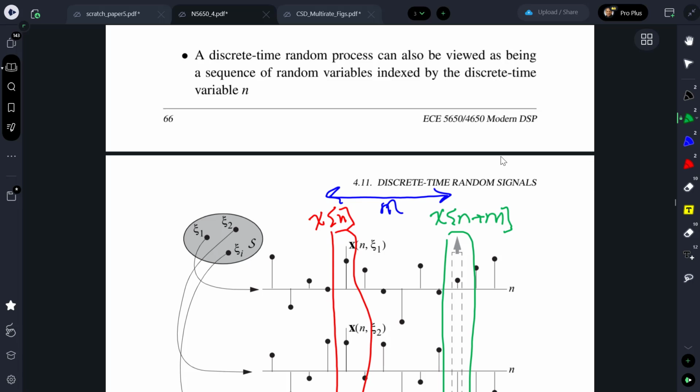A big exception to that would be if the processes have a periodicity to them, and that's called a cyclostationary property, where there's a periodicity. So if it was a cyclostationary process, it would periodically get strongly correlated and then get weakly correlated in between and then come back again. But excluding cyclostationary processes, ones that have periods, then they just fade away.